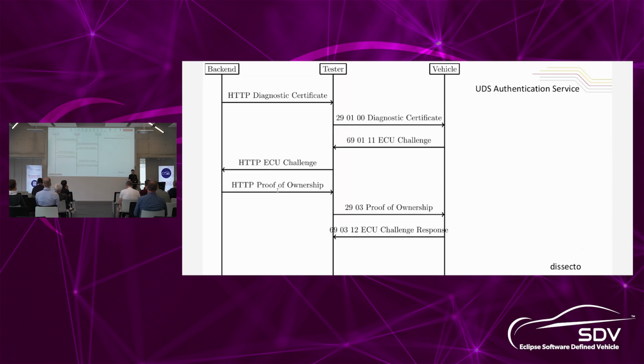One last thing, which is new, is full support of the UDS authentication service, so service 29. This is what modern diagnostic access looks like. We get a certificate from the OEM backend and send the certificate to the ECU. The ECU gives a challenge, we have the challenge solved by the OEM backend, and we send it back.